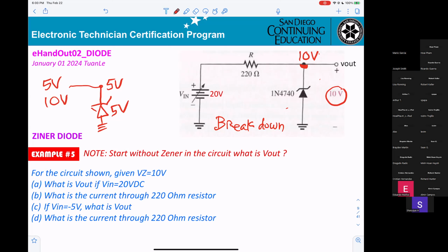No, no, no. The problem, like the problem right here. Okay? What they want is V out only 10 volt or less, cannot be higher. So that's why they connect the Zener here with the value 10. Any voltage here higher than 10 volt, the Zener breaks down, then you get 10 volt.